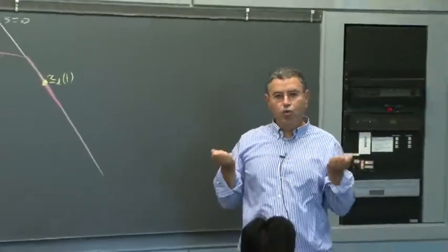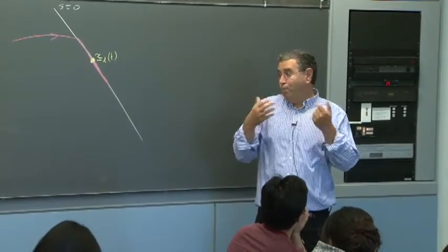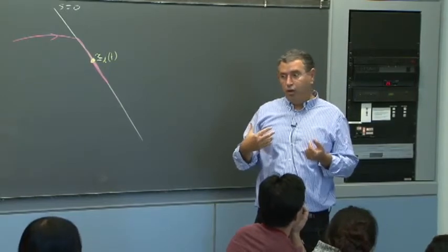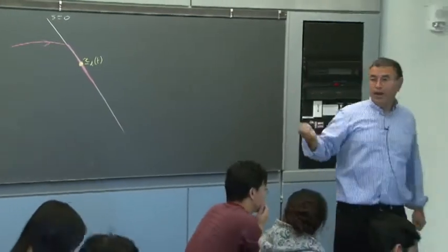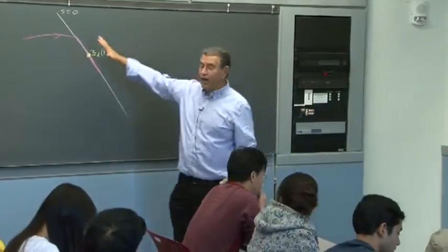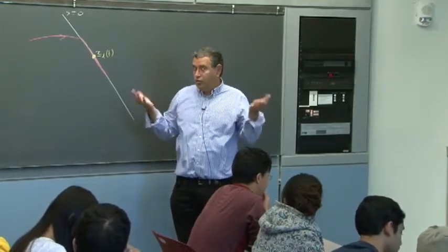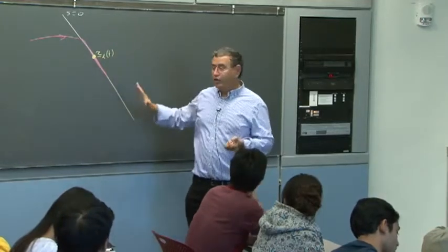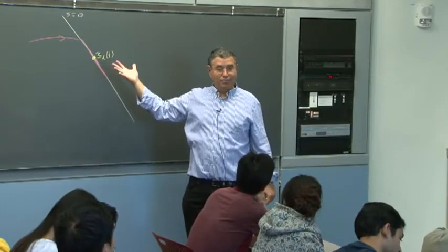The geometry says S equals 0 is both a place and a dynamics. It is the geometrical interpretation of replacing an nth order problem by a first order problem. S equals 0 is both a place and a dynamics. So if you know that it's invariant, once S equals 0 you stay at 0, then how you move on S equals 0 is completely defined by S itself.